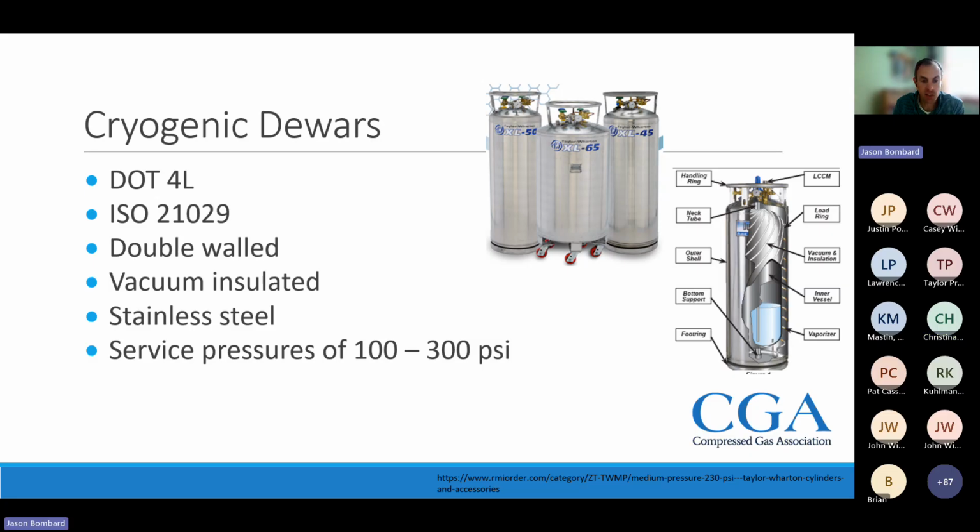Oh, the main difference is the construction. So a refillable cylinder is beefier. It's made for that cycling of pressure, empty, full, empty, full. The disposable cylinders are typically thinner, and they're made to essentially be pressurized once and then disposed of. So it has to do with the structural integrity of the cylinder. Gotcha. Thank you. No problem.